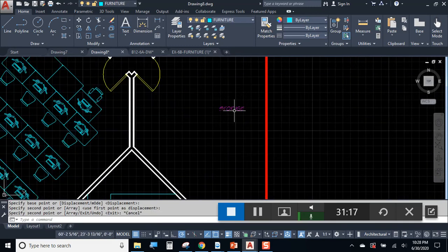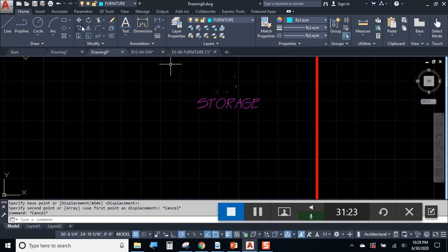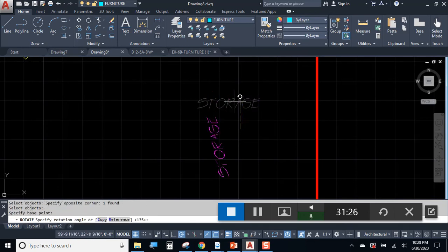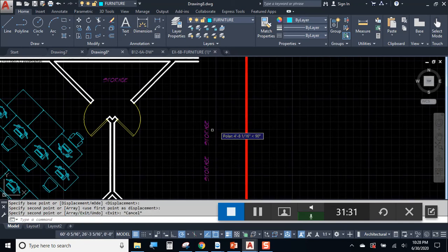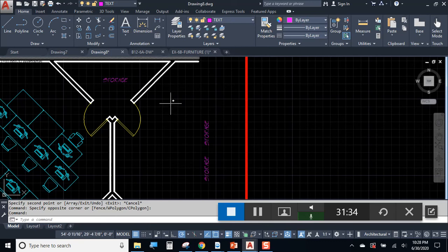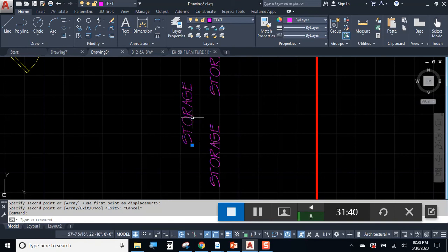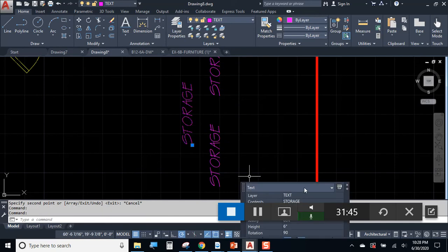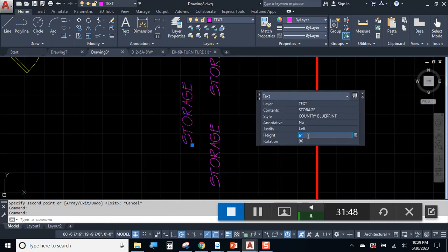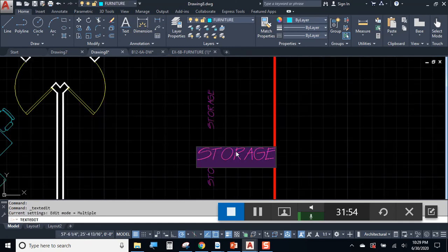And then on the side of the drawing, rotated at 90 degrees, we need some text. So, rotate. Okay. There is some big text in the drawing. The big text is the title of the drawing. So we'll go to the quick properties, and that text is not going to be 6, it's going to be 12. And the title is CAD Lab MS9.